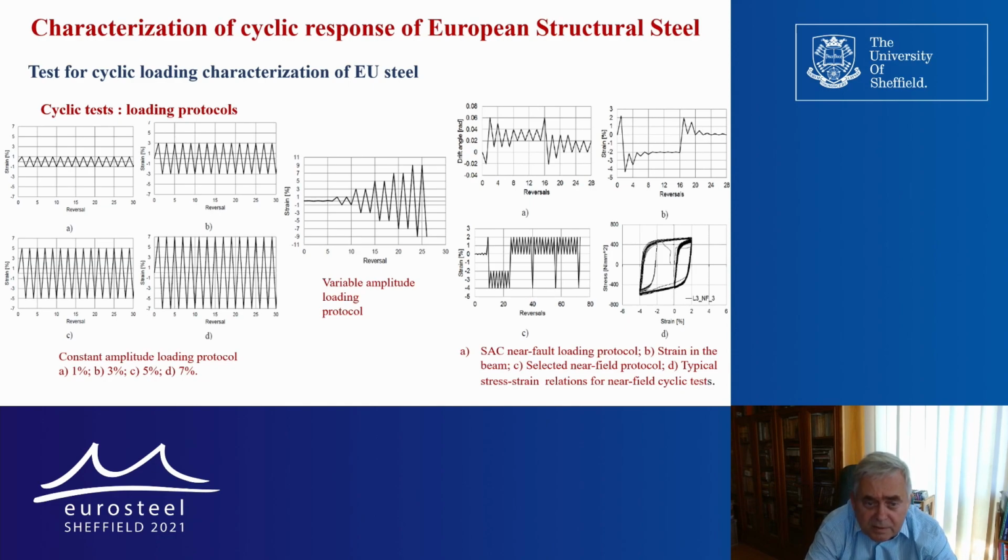We have used a variable amplitude protocol with increasing strain, and we have also investigated the so-called near fault loading protocol, where practically an irregular variation of the strain has been considered.